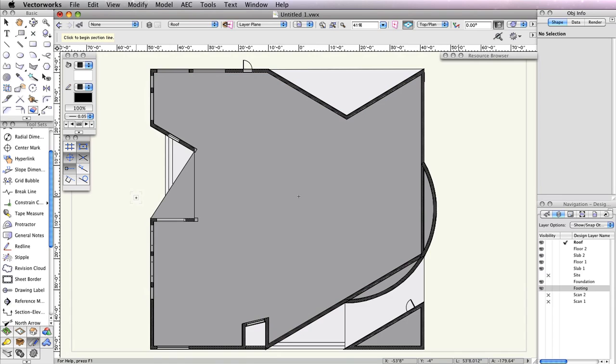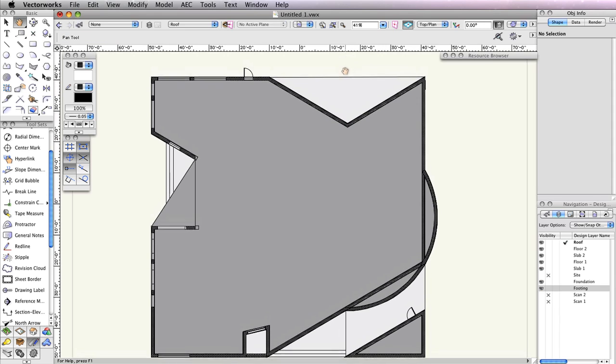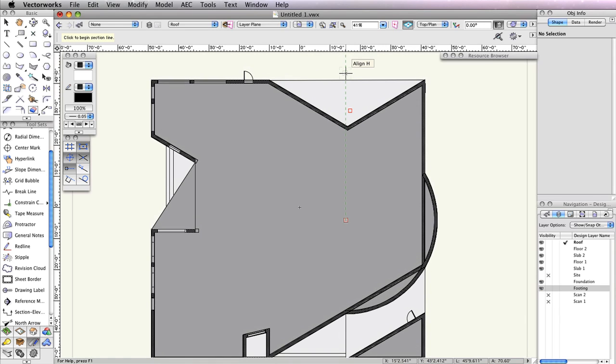Instead of the Create Viewport dialog box populating immediately, you need to tell Vectorworks where the section line should be and which side of the section plane to show. First, to draw the section line, snap to the center point of the circular floor in the auditorium. Hold your cursor there until the smart point is acquired. Once the smart point is acquired, move your cursor upward along the extension line from the smart point.